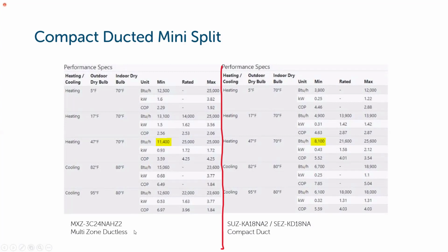Multi-zone heat pumps were pretty popular, where you have one outdoor condenser unit feeding, in this situation, the potential 3 indoor mini split heads. It seems like a good clean option where you just have a single condenser, you don't have 3 different condensers outside for 3 different heads. But there are impacts on output of heating and what that means to the individual rooms that are being fed by that single outdoor condenser.